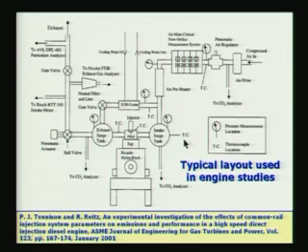So you see that a large number of pressure measurements and temperature measurements are involved, and apart from that, a few other important things. For example, you have the smoke meter. The exhaust is taken to a smoke meter, and we are talking about the opacity measurement. That is one of the measurements which is going to be there. You also have a particle analyzer to find out the diameter of the particles, the size distribution, the number, and so on.